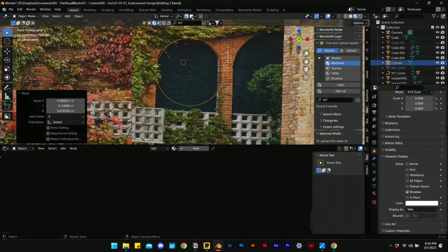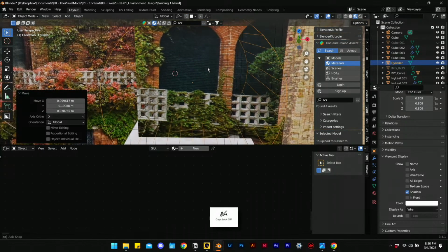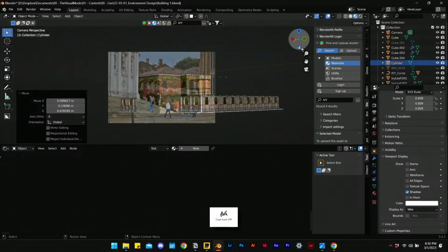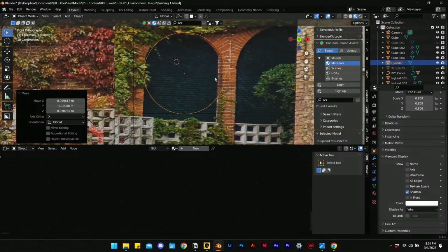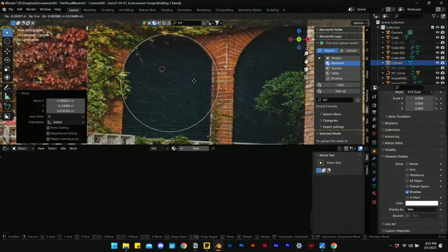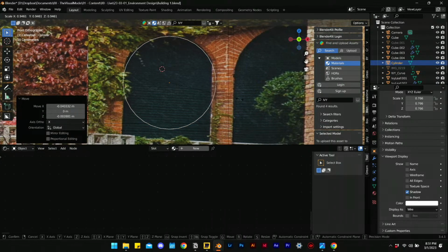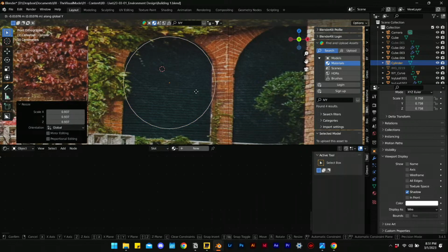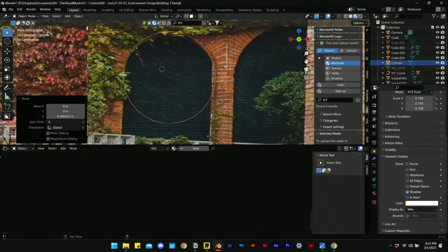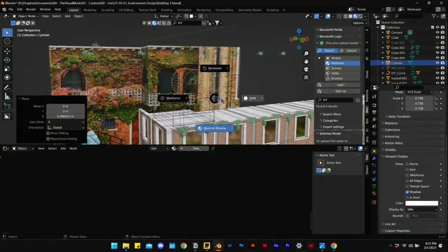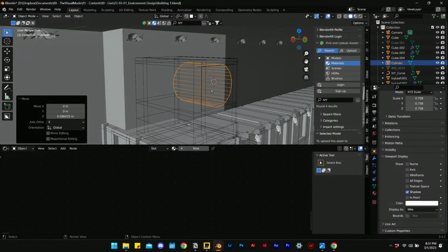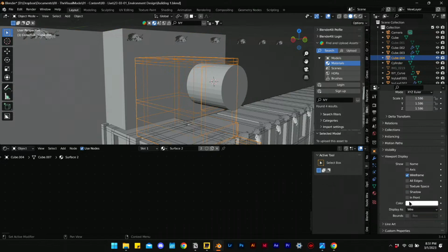It's not a perfect cylinder, the arch, obviously. So I can just stretch it in whatever axis I need to. Actually, it fits pretty great. I'm just going to go ahead and say it is a perfect cylinder. Okay, just have it fit right there. Go to my solid view, make sure that this is pushing out. And just like we did before, we're going to do a Boolean, but this time it's going to be a Boolean difference.